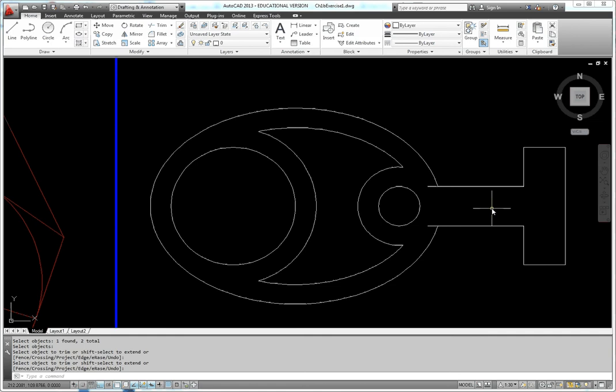And so now all I have to do is round some corners, put a chamfer or two in, and a hexagon over here. So I'm going to pick the fillet tool. I'm going to set my radius to 2 by going into the radius option, setting 2. And I'm also going to use the multiple option. So that'll allow me to create multiple fillets.